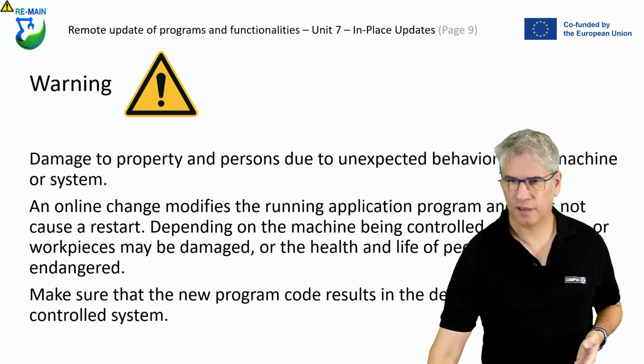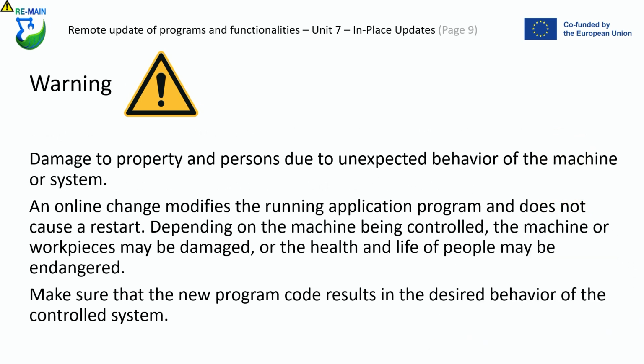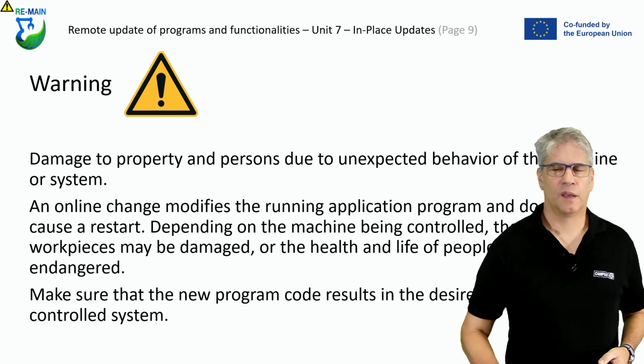And that's why most PLC manufacturers give warnings that damage to properties and persons due to unexpected behavior could happen, that there is no restart, therefore something could be damaged, the workpiece, or even people could be harmed, and you have to make sure that your new program code really results in the desired behavior of the control system.